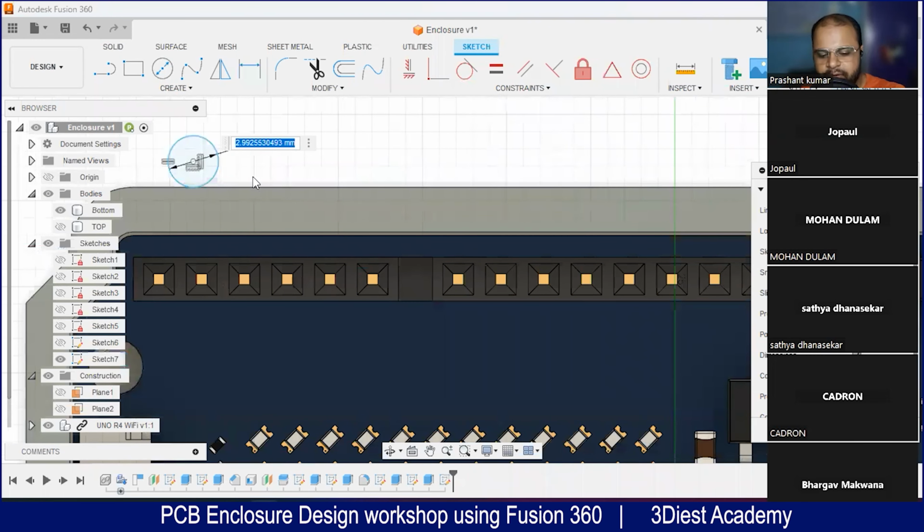And also since we're going to 3D print it, we are going to apply some chamfers onto the bottom edges, right? So we'll select the bottom edges and apply a chamfer of maybe 45-degree angle. We'll give it some chamfer distance, let's say how much it is able to make, maybe 3 millimeter, not working. 2.5, not working. 2.6, it's working. If you're not sure how much is going to work, you can just consider, right? Here I'm considering 2.95.